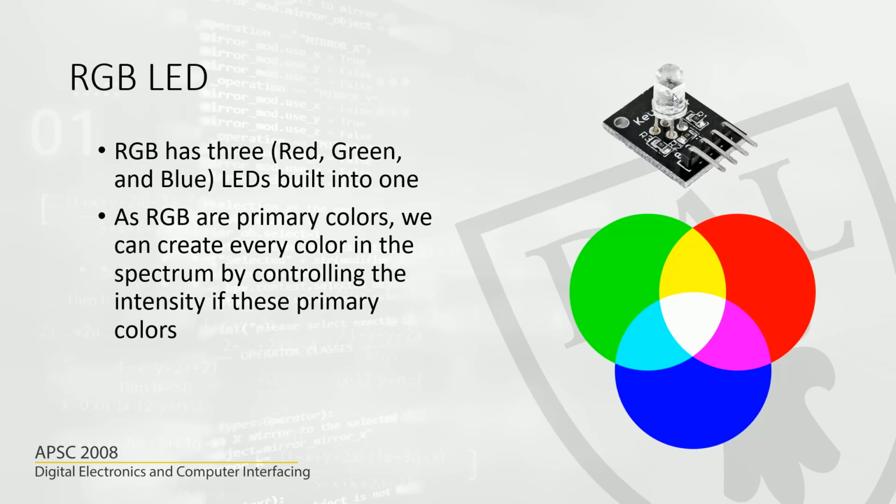So ground has to be connected to the ground, RGB will be connected to 3 different pins, and to those 3 different pins we will apply anything between 0 and 255. So this is an 8-bit system. Just to mimic that, we are using these numbers. So we'll pass an integer somewhere between 0 and 255, and then based on that you will get the output.